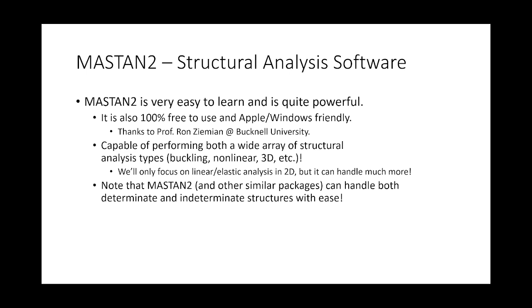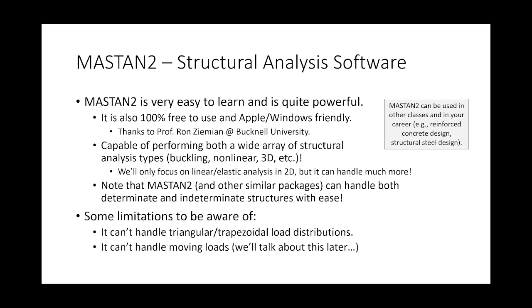One of the things about MASTAN, and this is true of all other structural analysis packages, is that it makes no distinction between a structure that is statically determinate and one that's indeterminate. It handles them both the same way. And so I kind of want to talk a little bit about indeterminate analysis today, so that you have an understanding of what the challenges are, how would you approach it, and how MASTAN does it. This program can also be used for steel design and concrete design, because whenever you take those courses, you have to have some basic skills in structural analysis in order to design the elements. That's something I wanted to mention.